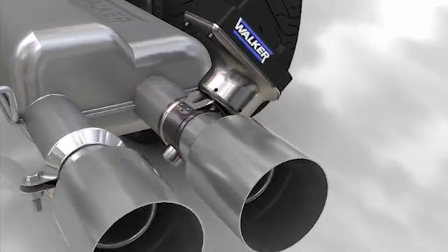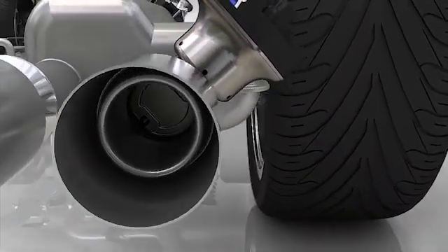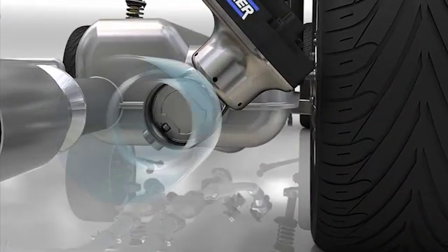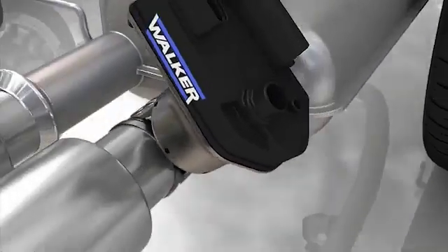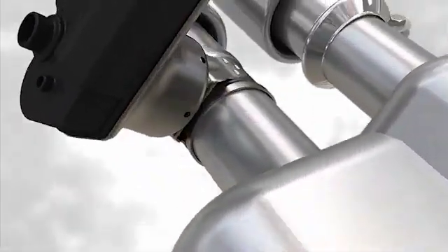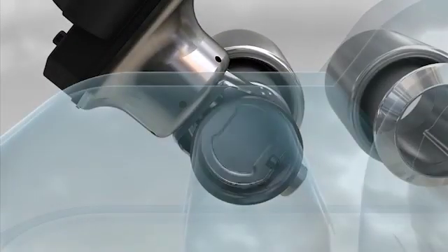The structure and function of this valve is very similar to that previously explained, except that the disc which blocks the exit of the exhaust gases has no hole in its center, i.e., it can, under certain conditions, fully close the flow of exhaust gases out into the atmosphere.